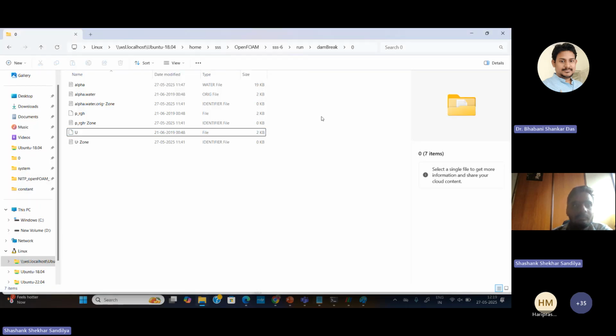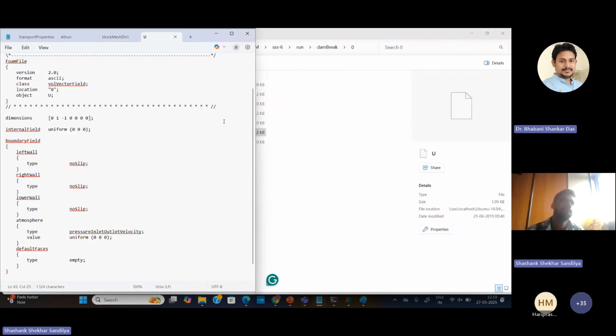Okay. Here you can see, go to the previous boundary conditions slide. In the boundary condition, for no slip, it is written as noSlip, no need to write that the velocity is zero. In Fluent or in any other software where you are imposing a boundary condition, at that time you have to give the velocity value as zero at the boundary. So here the command is noSlip, with n in small case and S capital. Only in text form we can give it and it will be executed as a no slip condition. No need to write the velocity value, unlike other software like Flow 3D and Fluent, where you have to give some value. But here you can write simply this.